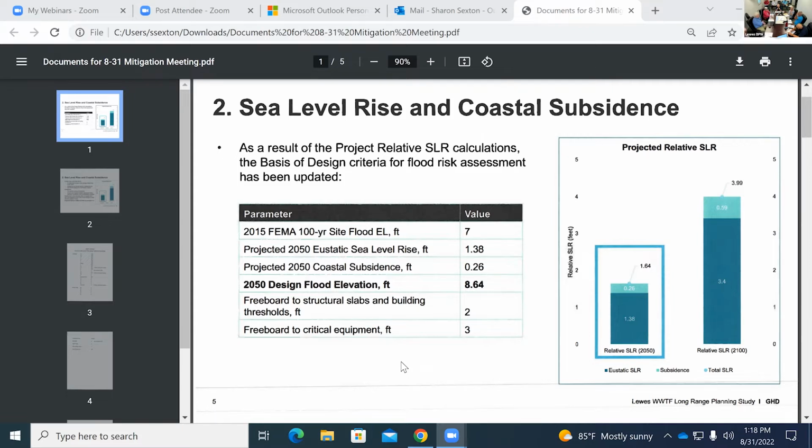Well, again, this one would have been 11.6 at 7. Yeah, so that's 6 inches higher than what we were estimating at 11. Now we have other people here that are familiar with that too. What we've been doing is the 18 inches of freeboard plus the 1.38, so we're roughly in the 32 to 35 inch range. For instance, the pump station at Waterfront Preserve, the pump station at Hauling Cove, the pump station at Tower Hill, those are all set at roughly 3 feet above the floodplain elevation.